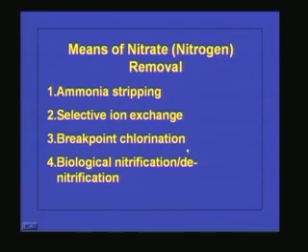Another one is breakpoint chlorination. We have seen this when we were discussing chlorination. If ammonia is present, monochloramine, dichloramine, trichloramine, etc. will be forming, and if you again add chlorine, this trichloramine will break up into nitrogen gas and chloride.